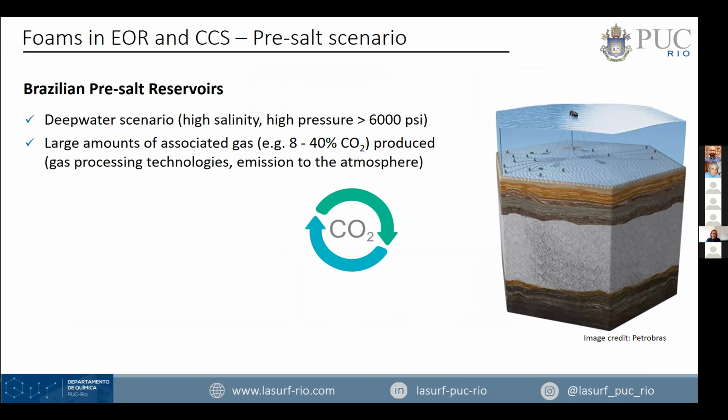Another problem is the large amounts of associated gas, in particular CO2 in high amounts, that is produced from these wells. This requires more complex gas processing technologies, and it can become an environmental problem, because the gas that is produced cannot be burned or simply released to the environment because of this great amount of CO2.